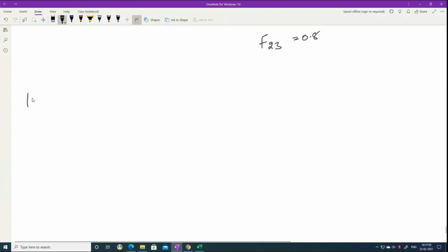Okay, what are the resistances? You calculate. So RS1, if I take, what is the formula? (1 minus epsilon 1) by (epsilon 1 into A1) is the formula. So what is the epsilon 1 value? It is 0.